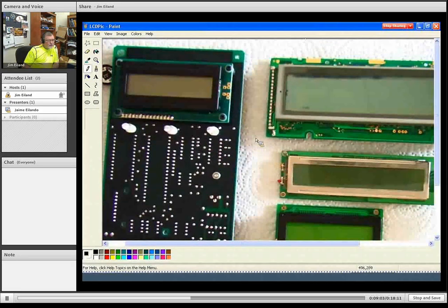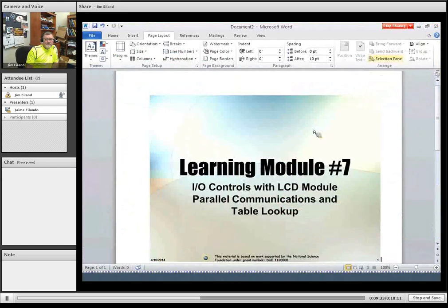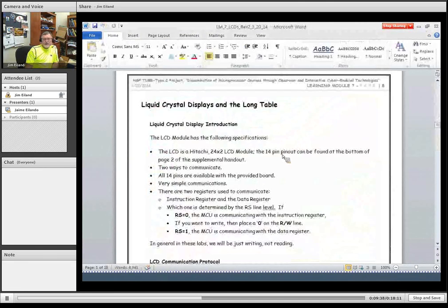Now, one thing I wanted to note was that once you get an LCD on your board connected, you have a viewport on what's going on inside the chip for debugging purposes, rather than just flashing an LED if you made it to a certain subroutine. Now you can actually look at values. It's one of the first experiments I do with the class, so that we have a viewport that we're able to get to very quickly.